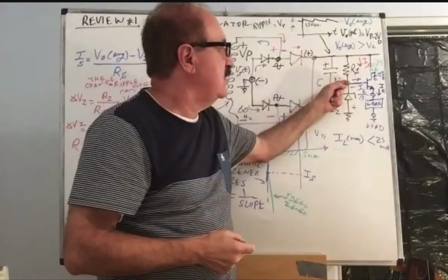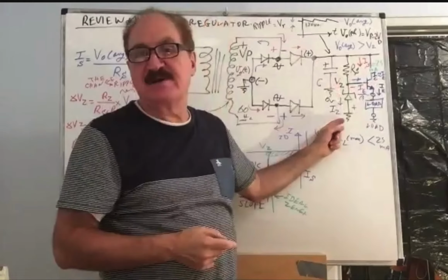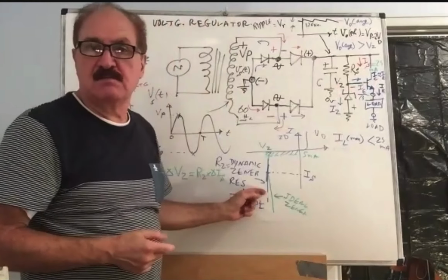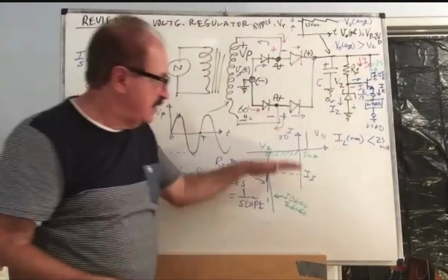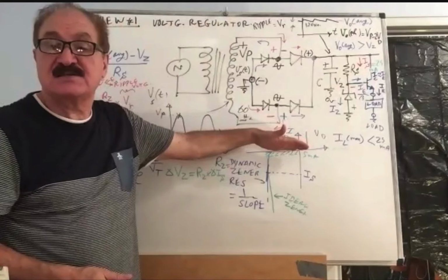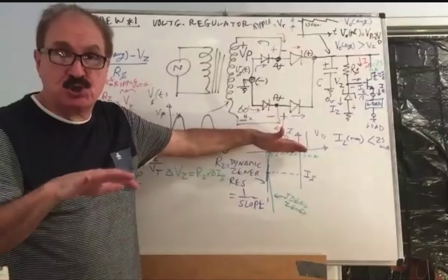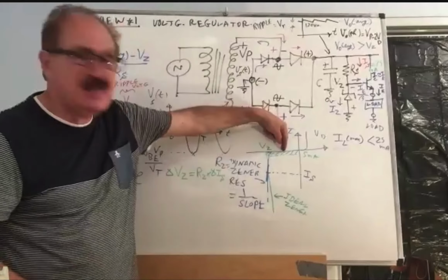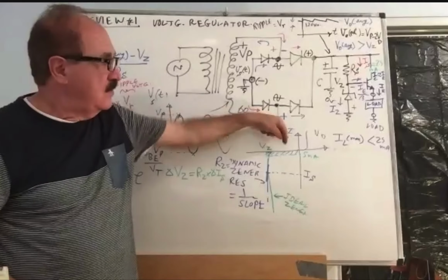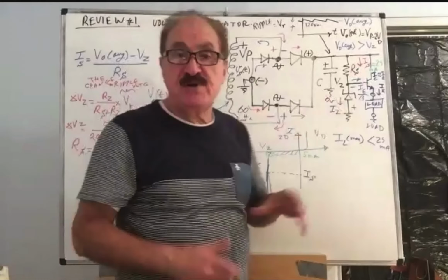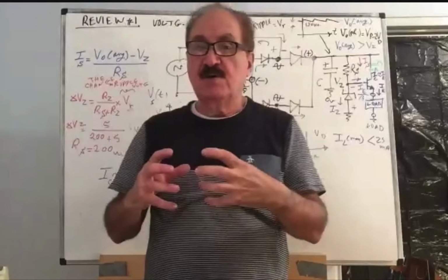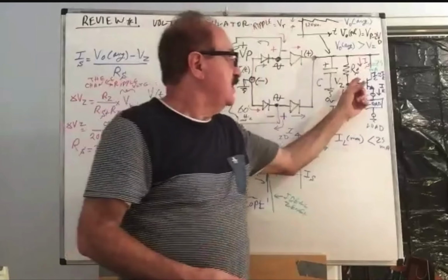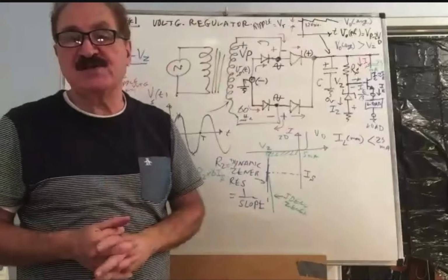So the base current will take 1 milli off of the Zener assembly. So the Zener current will change from 25 to 24. Fine, that is way safe and well into the Zener stable region. We will not hit that corner. So this pre-regulator will function properly because it will be boosted by the current gain capability of that transistor.